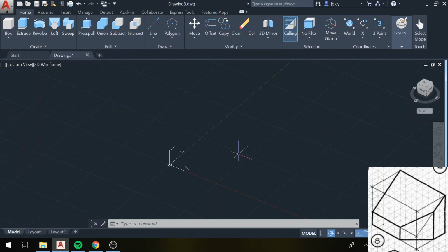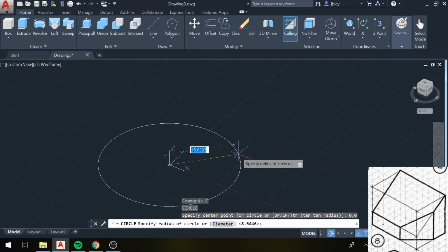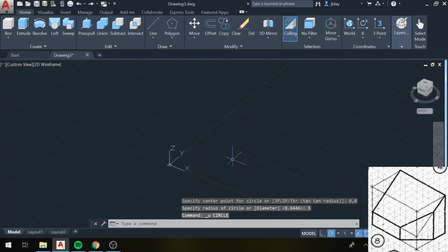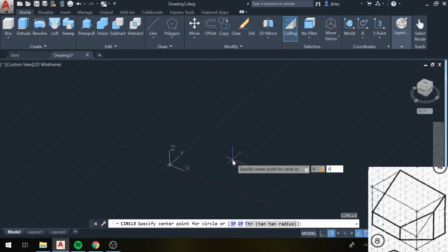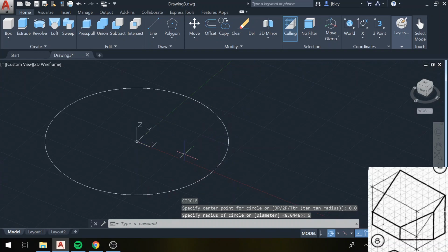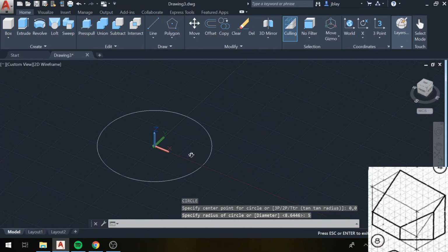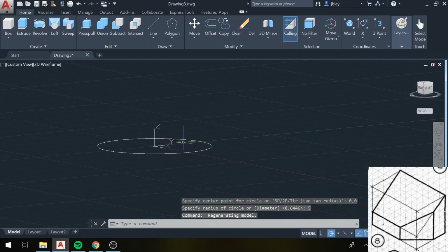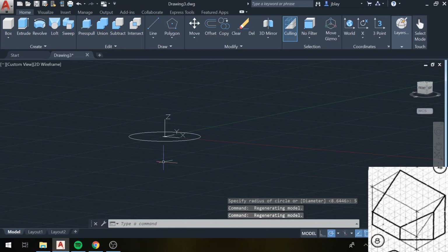So let me get started by just drawing a basic circle. Let me just draw that again. I think I did something weird. Radius of the circle is going to be 5, so the diameter is 10. If I want to use the Loft command, I need to draw 2 sketches. So this is going to be my first sketch, and then I need to put one that's higher or alternatively lower than the circle I've drawn.